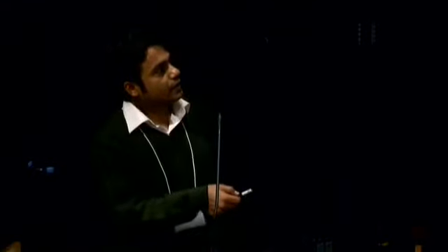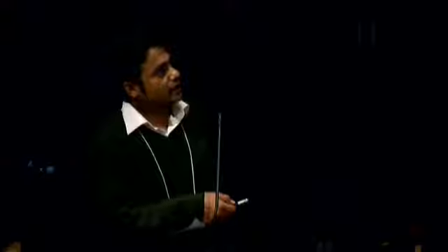I will talk about that. So I will quickly go through the bit cell overview. The bit cell consists of one transistor and an MTJ, and the MTJ has two ferromagnetic layers, and the information is stored in the form of the relative orientation of the magnetization. When the two magnetizations are oriented in the parallel direction, we have a low resistance state called RP, and when they are anti-parallel, it's the high resistance state.